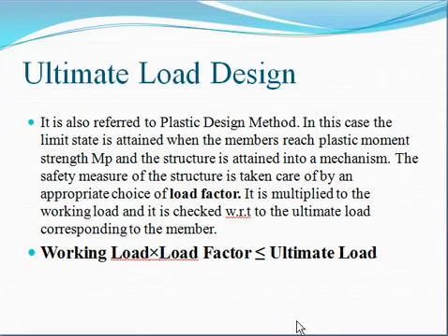A section is said to form a plastic hinge when all the fibers are yielded, but the structure continues to resist load until a sufficient number of plastic hinges are formed to transform the structure into a collapse mechanism.